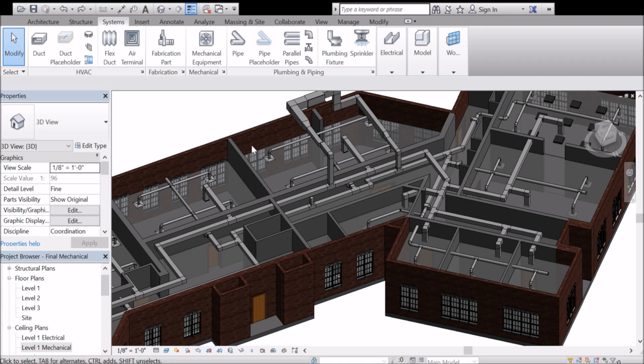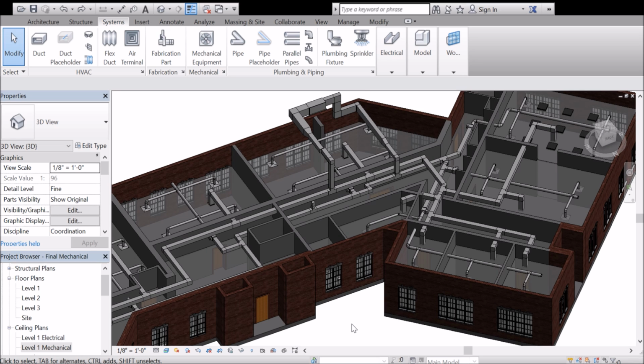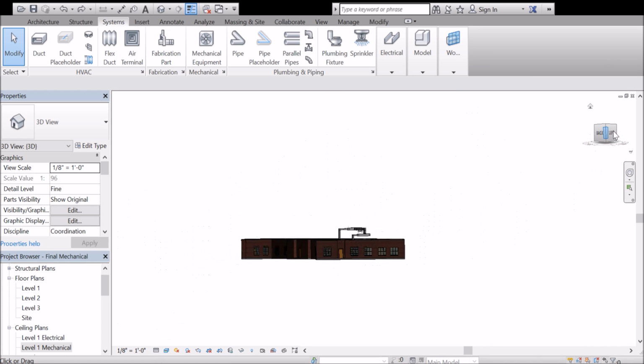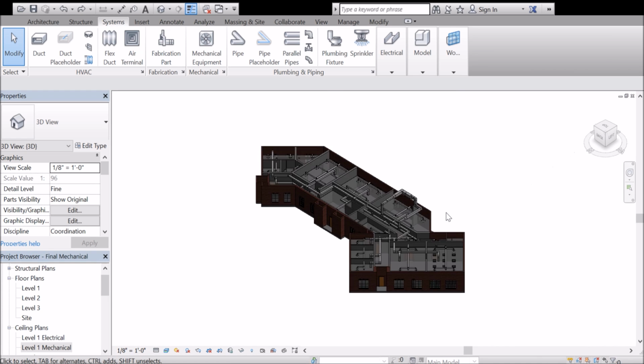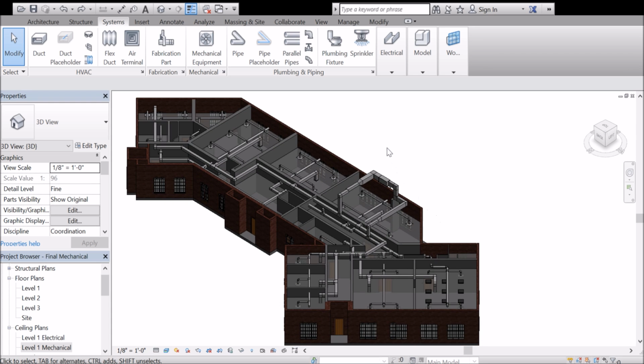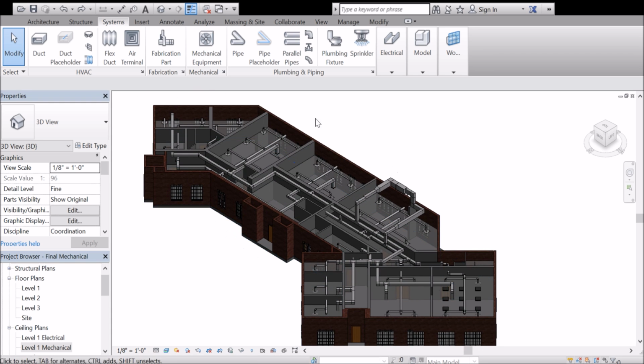So you're going to want like a little section of wall, like this area here in the front of my building would work well. Just a little section that is actually sealed off that you can run ducts the length of your building in. So either a walled off section, or you'll have to draw a wall in to hide them or something. But if we run into that problem, we'll work through it and figure stuff out. Otherwise, that is everything for your mechanical systems. So if you can get all of that figured out, you're looking pretty good.